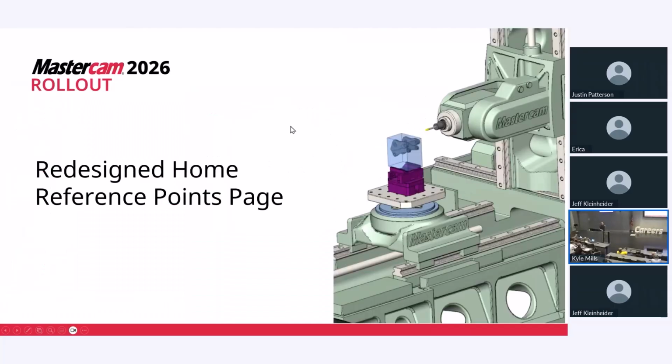The next one I'll go over is we've done a little bit of a change to the reference points page. Anybody ever use that? Probably especially my 5-axis guys, if they want to get out somewhere nice and safe at the end of a toolpath. They've done a little bit of work, so now you can use the tool plane instead of just the WCS.